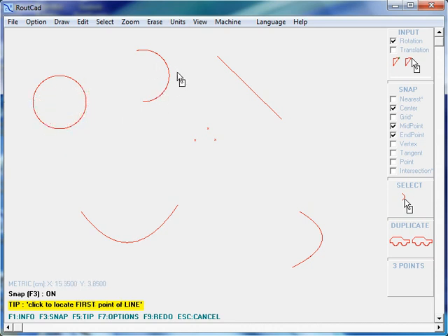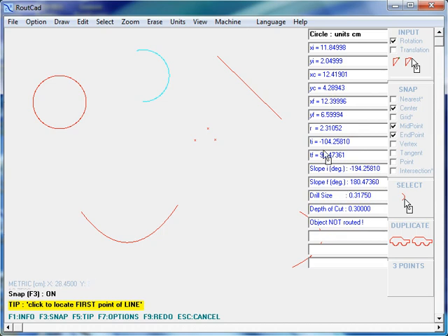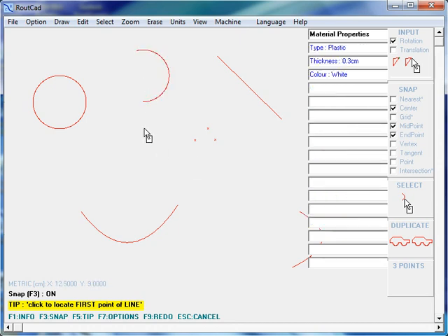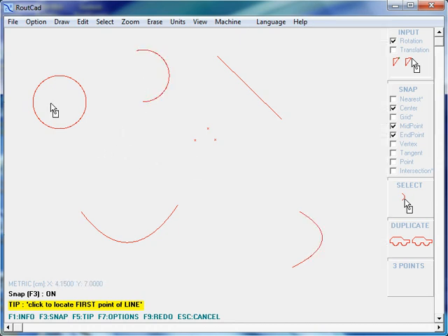You'll notice the arc doesn't have that. The arc only has a center over there, and the beginning of the arc is whatever that arc is over there, and whatever that arc is, finish. So a full circle starts at 0, finishes at 360, and this arc starts at another angle, which is -104, and finishes at 90 degrees down, 90 degrees. Now, a full circle also has a center that you can click to.